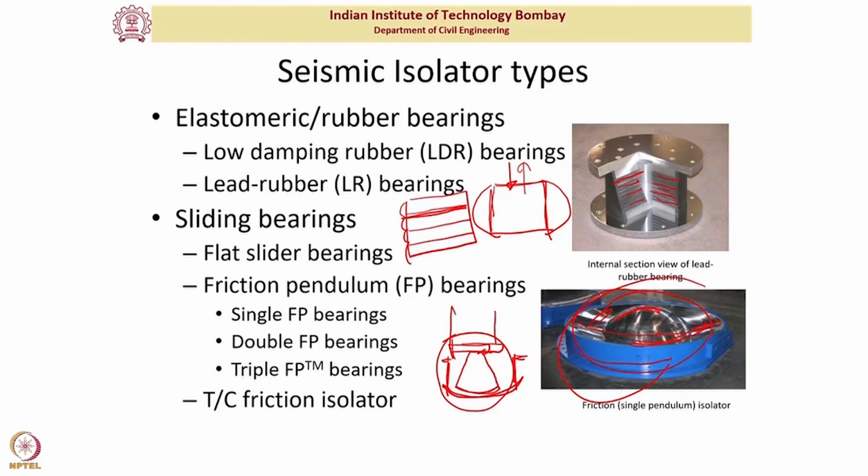So the shear modulus might change. Those issues are there with both of these, but typically those are taken care of in the design itself by estimating that, let us say, over 15-20 years the shear modulus is going to increase by 10%. So we do bounding analysis saying that even after changing the property, my structure should still be able to sustain those loads and deformation demand from the earthquake.